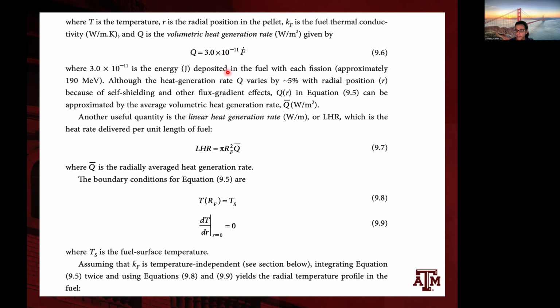And basically, now the only unknown is the fission rate, and the fission rate is dependent on the operating conditions, the reactor, and the fuel. However, the number for light water reactors is known. It's about 10 to 19 fissions per meter cube second. And this number would be given in the input file, but basically this is how we use nuclear engineering calculation to calculate this heat generation that we use as a source term in our equation. So it's an input in that input file.